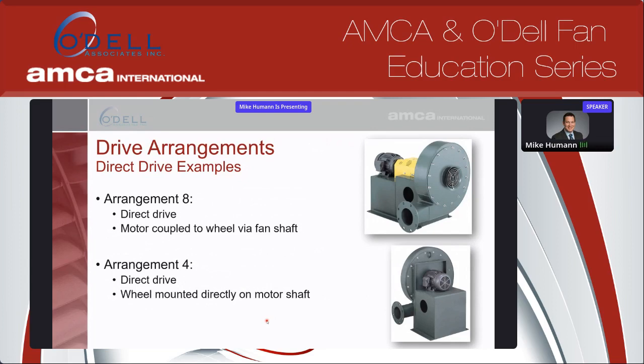An arrangement 4, you can see down below, is more compact. There's also less cost impact there, so you have a lower cost fan. You can use an arrangement 4 up to about 200 degrees Fahrenheit as standard. 100 degrees C or so is pretty typical. Beyond that, you have to start considering all the heat that's going to be generated and taken in that motor.